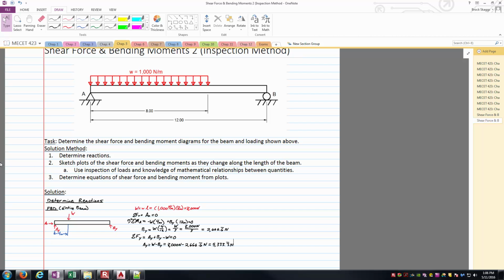which is the statically equivalent point force. Then it's just a matter of where to place this statically equivalent point force along the length of the beam. The idea is that you place it at the x-bar location, or the horizontal coordinate of the centroid to be more specific, associated with the distributed load area that's being bounded by the curve. In this case, the curve is just a straight line, a constant 1,000 newtons per meter, so essentially we're at half the base of that rectangle, 8 over 2, or 4 meters.